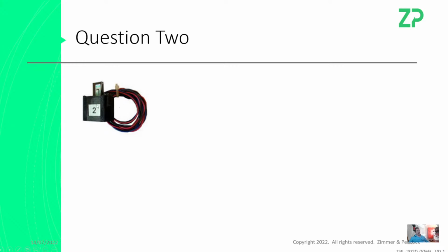By potting, I mean we take the sensor, we leave the sensing end exposed, but we then have to really protect the electrical connection. Essentially this box is almost completely filled with epoxy, because we don't want any ingression of liquid. And when we've done that, then these cables are fairly okay. We can just pull these cables out, put them anywhere.